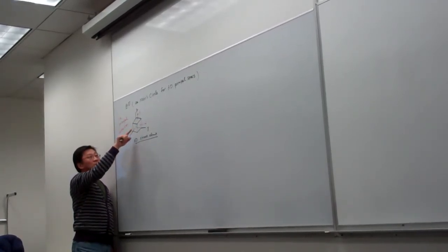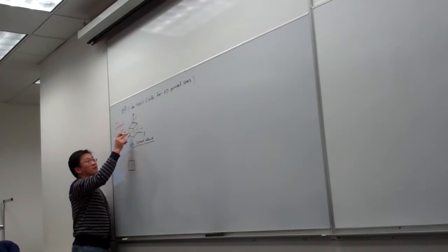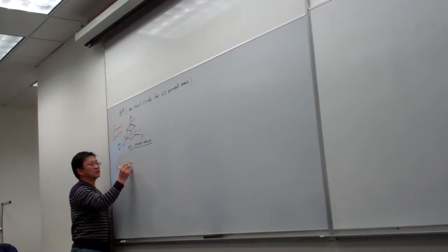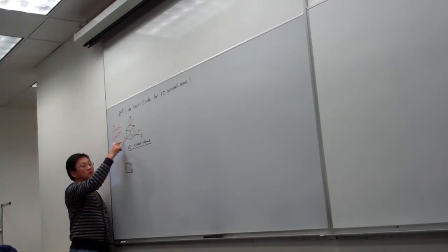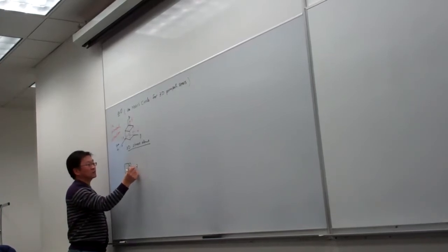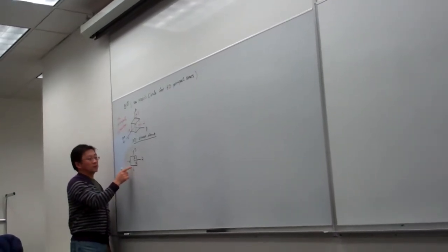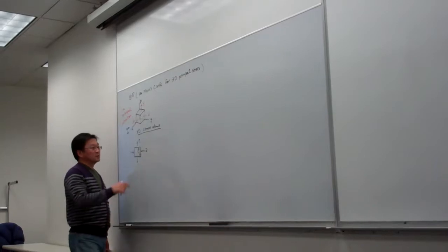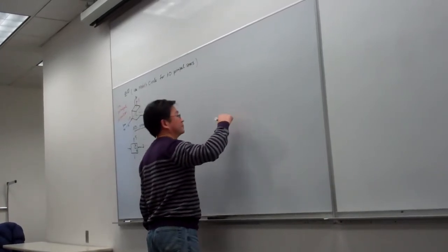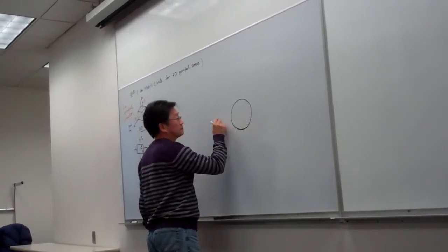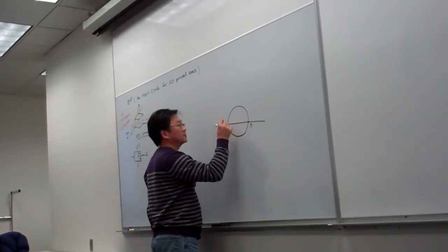So that means once you're looking into this element, in front of you, you see the y-axis and the z-axis only, because you are in the x direction. So in front of you, you wouldn't see the 10. That means the distribution of the stress is 2 and 5. So with this, we can draw the Mohr circles quickly. For this case, the Mohr circle will be, let me draw here. One is 5 here, one is minus 2 here.